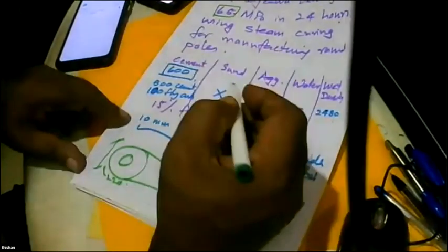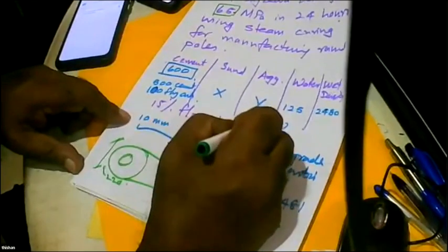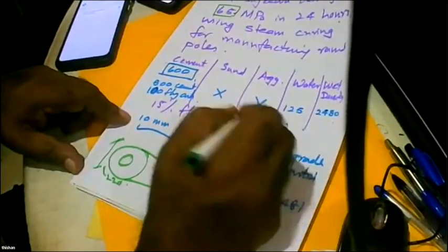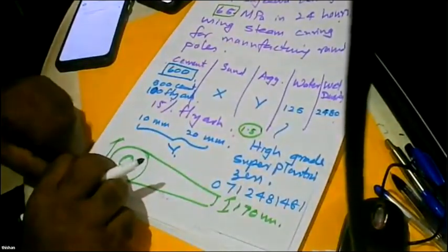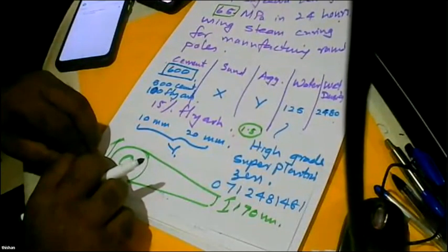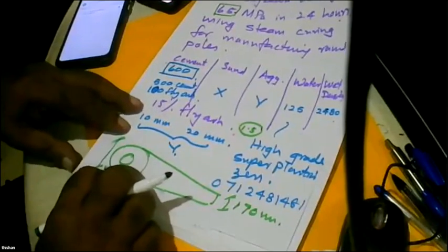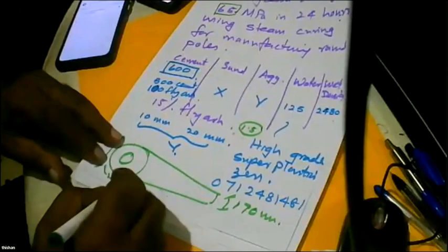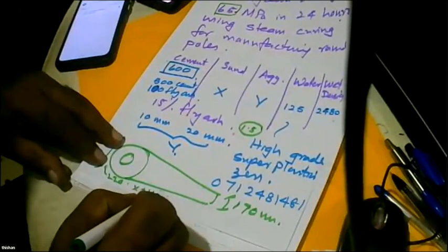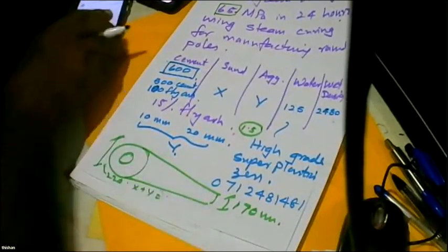I said, okay, I'm going to use a 1.5 ratio. Why? Because I need to compact it properly. To compact it properly in a small section, it's good to have a lot of sand rather than a lot of aggregate. So I said, okay, I'm going for a 1.5 ratio. So if you look at the numbers, x plus y became 2480.